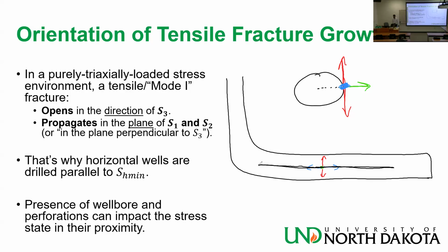It worked against theta theta. Now you understand why I always use blue for the axial stress and red for the tangential stress, because they are always the ones inducing longitudinal or transverse fractures. It doesn't change if you change the angle on the wellbore cross section.